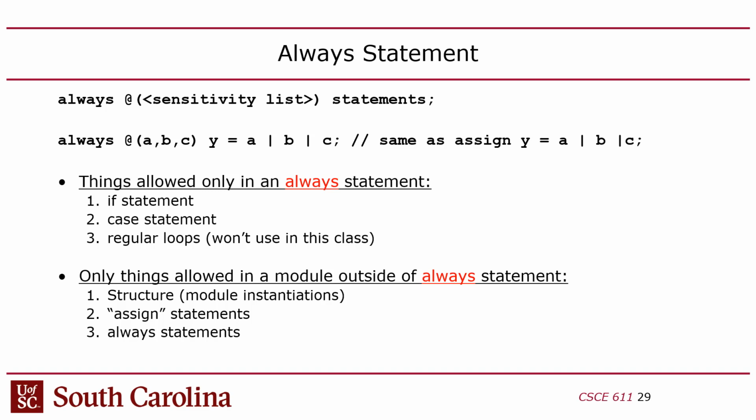You can also use them for combinational logic, but then why not use an assign statement? There are 2 different behavioral things that we're learning here. One is the assign statement, which cannot be clocked. It's only for combinational logic, lookup tables, or truth tables, basically Boolean logic. The always statement is mainly used for clocked, sequential logic. But you can also use an always statement to make combinational logic, in which case it's just a complex form of the assign statement. You guys with me?